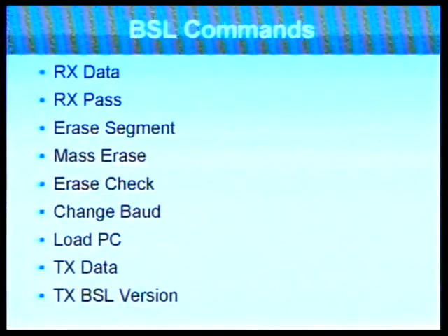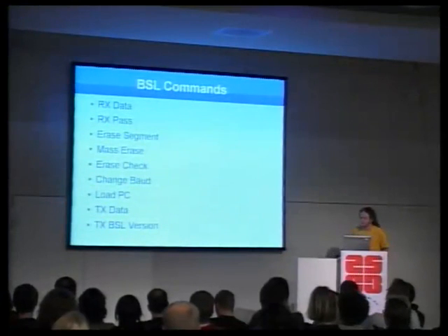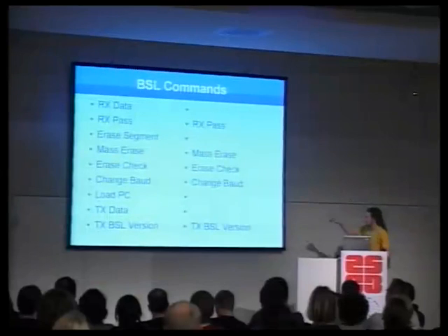So there are the different commands that you can use with it. You can receive data, and that means that you're telling the board, the victim, to receive data. You can tell it to receive a password, you can erase memory, you can erase all of memory, you can see whether or not memory has been erased, and all of these things. But only the ones in the right column can be accessed without a password. And some, like the change baud command, now require a password in more modern versions.